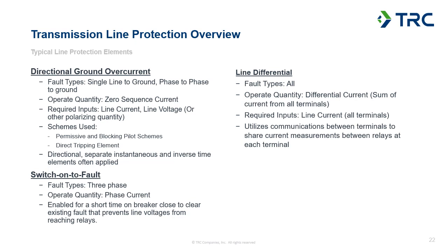Directional ground overcurrent protection is applied in a couple different schemes. Usually we would apply an instantaneous and inverse time type element, maybe used as part of a pilot scheme, a communication assisted type scheme, if needed.